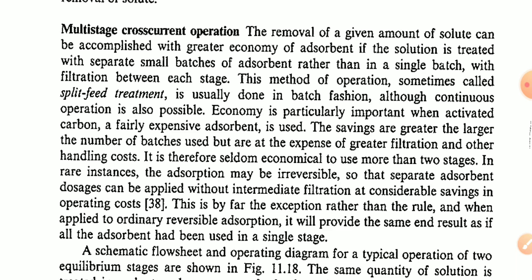In a rare instance, the adsorption may be an irreversible process, so that separate adsorbent dosages can be applied without intermediate filtration, at a considerable saving in operating cost. This is by far the exception rather than the rule, and when applied to ordinary reversible adsorption, it will provide the same end result as if all the adsorbent had been used in a single stage.